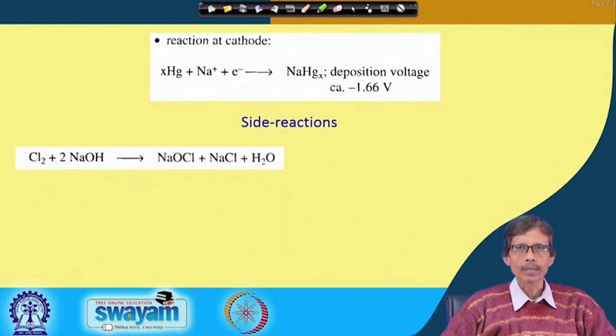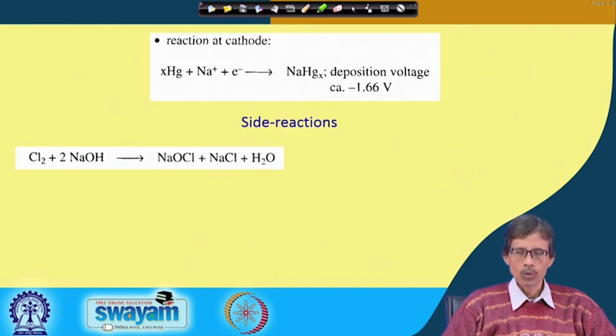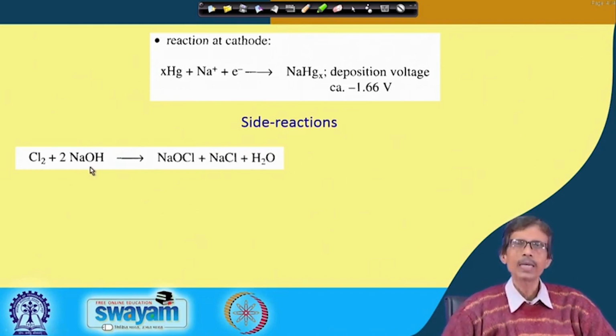But we should also consider some of the side reactions while you produce sodium hydroxide altogether. So, we will be producing sodium hydroxide as well as hydrogen, but some side reactions will be destroying our target materials, chlorine as well as sodium hydroxide, because these two things will be there. And during the passage of this chlorine leaving your chamber, your chlorine gas can react with the produced sodium hydroxide, forming sodium hypochlorite. That we will also discuss afterwards, how we can make sodium hypochlorite very quickly, which is a very good bleaching reagent and is also industrially very important.